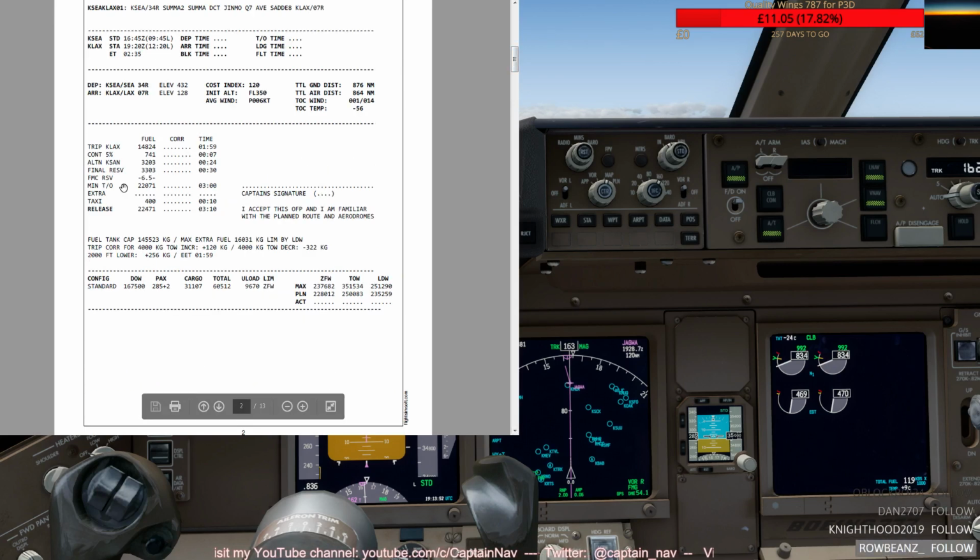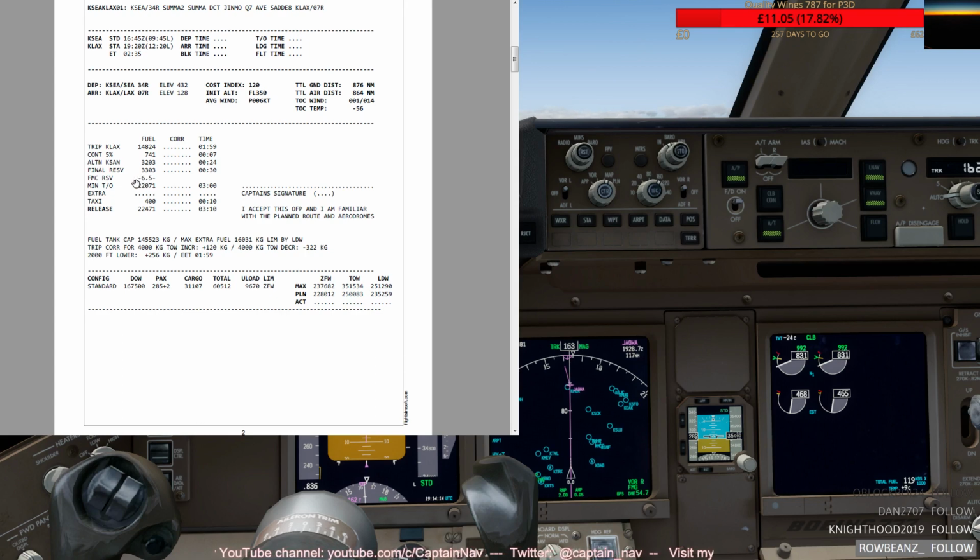So you get close to destination, and today, for example, the diversion fuel, as I call it, is 6.5 tons. So you'll be close to destination, you're a little bit unsure, there's maybe a little bit of holding, or after holding you think that your approach is gonna burn more fuel, and you're gonna basically land below the 6.5.